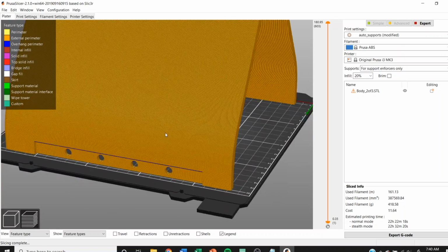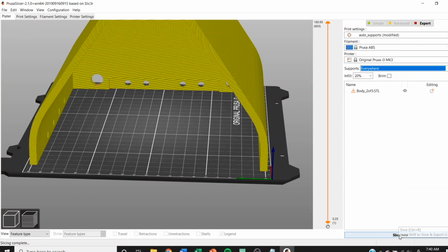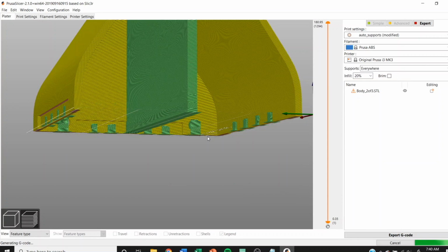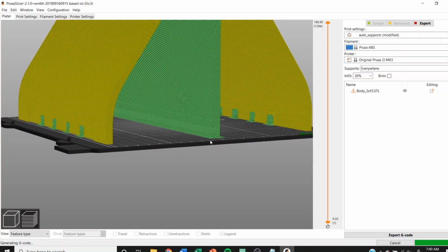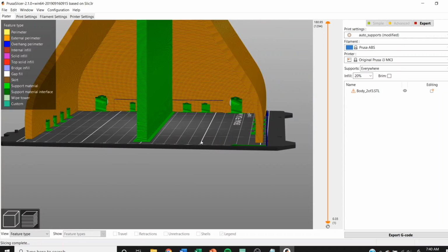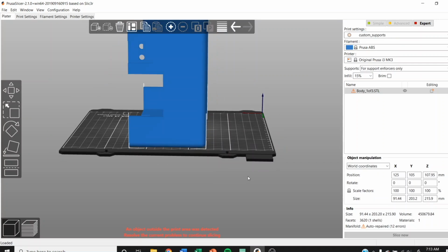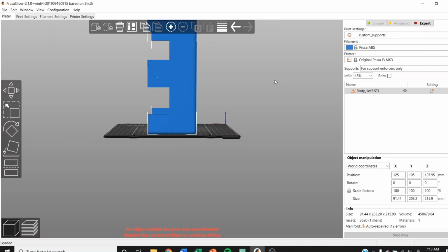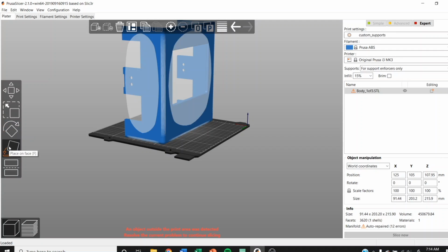Although I would always recommend that you try to only print small to medium things. We shouldn't really force the printer to go out towards its limits. Once you slice, we see we have auto-generated supports, and they look pretty good, but if you're not entirely confident in their actual stability or how much they would help, you can always create your own custom supports.